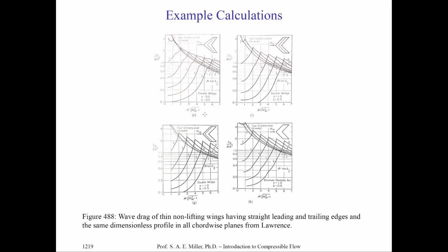This is nothing but the aspect ratio times beta for the swept wings, which we discovered and discussed in this class. On the y-axis, we have coefficient of drag divided by the aspect ratio times the thickness ratio squared. And so the y-axis is non-dimensional drag, and the x-axis is aspect ratio times beta, which is the non-dimensional coefficient we just discussed with our transformation.